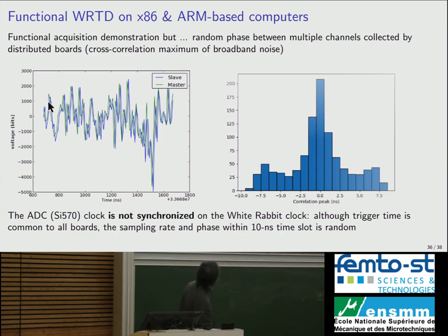So what Matisse did, he collected data over the network where we had 10 megahertz distributed over two boards separated by 2 kilometers, data sampling at 100 megasample per second, so we have 10 samples per period, and you expect the phase to be the same on any point of your node. And if you look at the phase distribution, you get something that is distributed.